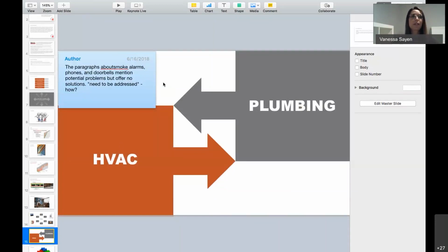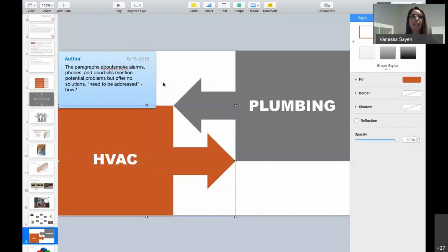Okay. And then there's other areas too. Like I mentioned, the HVAC system components can potentially create noise and can be heard through the vents, like that example I just mentioned. But how can we prevent this, right? There are inline silencers available, little tubes that connect to your AC, and they come in 5-inch or 6-inch diameters. Or you can simply lengthen the run of the ductwork from the main unit to a room by using S-turns. This will help greatly to reduce the noise level.